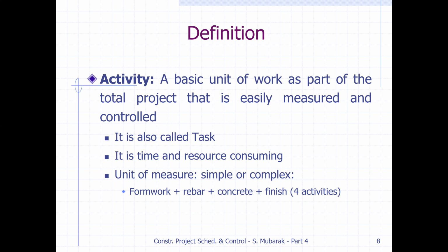We can decide how much time is required by dividing it into activities: fixing of formwork, fixing of the reinforcement or rebars, casting of concrete, doing the finishing work, and then maybe taking out or stripping the formwork.